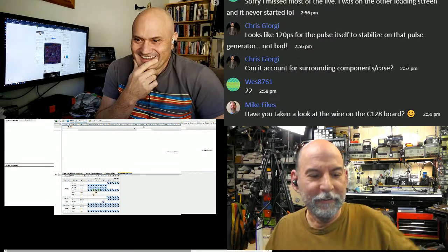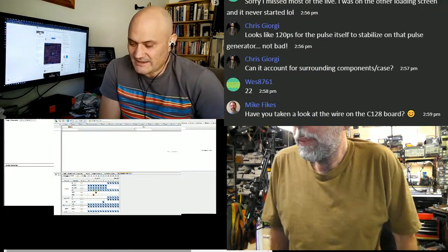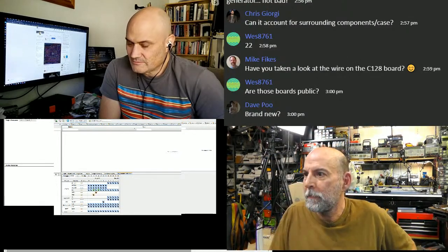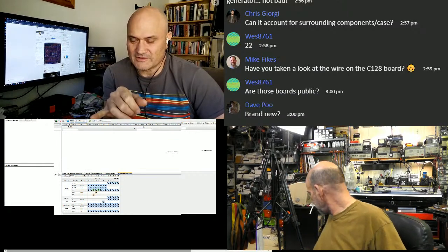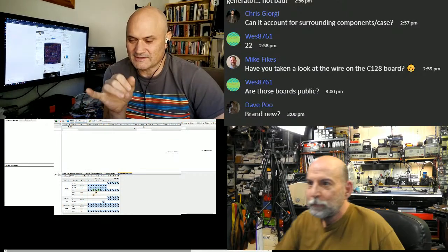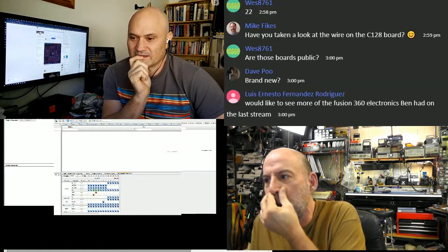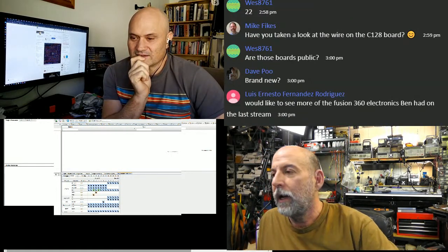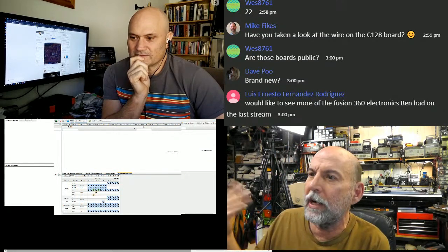But yes, I should. I've got some Z80s. The 128 used a different 6502. It was a MOS 80-something, right? 8510. It's a 6502 with a port built into it, down at zero page, and they originally used it as an I/O port.